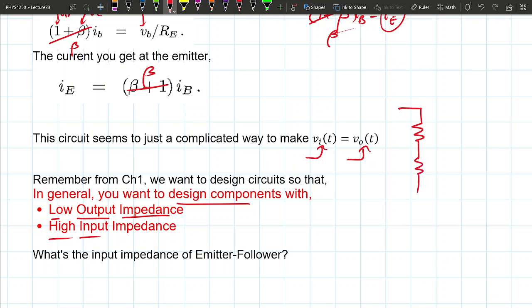When you put 1 meg ohm here and 1 meg ohm here, this makes a very large output impedance, and that affected whatever the R load was doing. You guys remember that from lab 1. So what you're supposed to do is put a tiny resistor here, maybe 100 ohm here and 100 ohm here, then it won't affect the output.